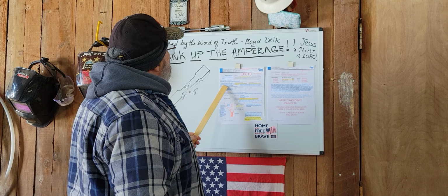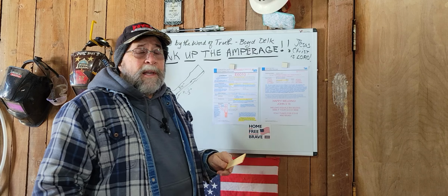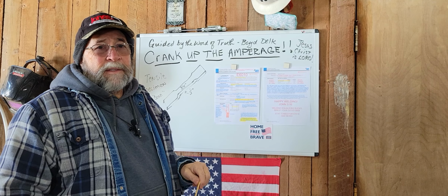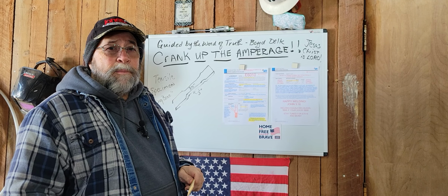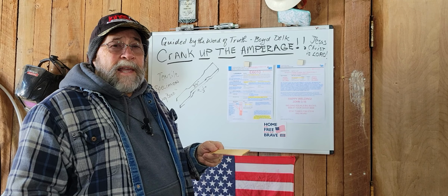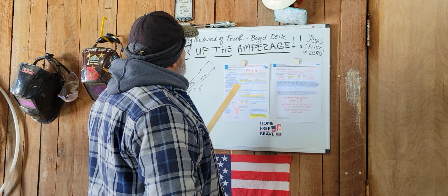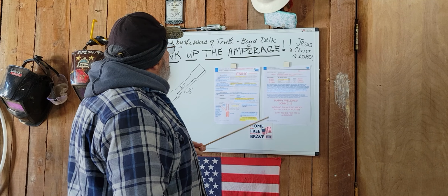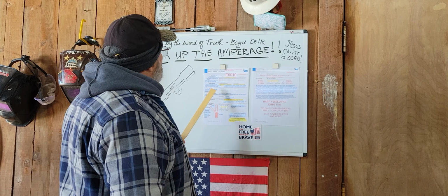Okay, so in general, for quality welds, base metal should always be cleaned. Don't ever make a weld. If you're trying to make a quality weld, the very first thing you want to do is clean the base metal. This rod right here will burn through dirt, rust, it doesn't matter, paint. That's another thing I like about it, but it's okay to understand and know that. But for quality welds, always clean your base metal by mechanical means. You can use grinders or whatever, but you get the idea of cleaning base metal.